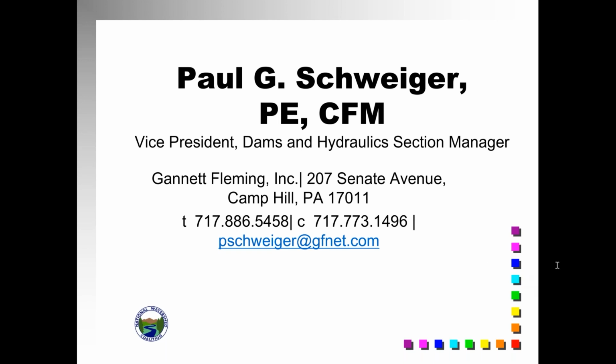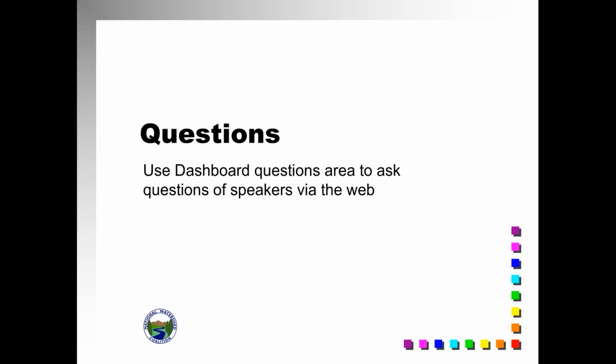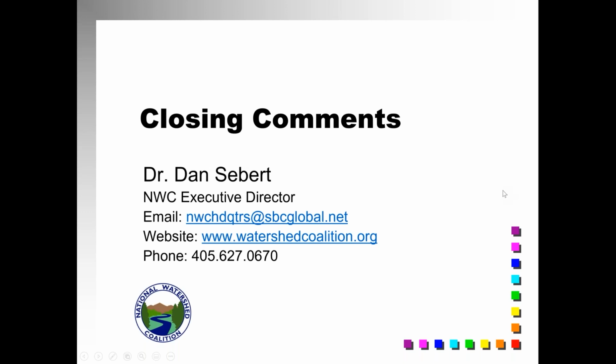A lot of modifications are often done with good intentions, but they have consequences that are not anticipated and can create a real problem. A good example was the farmer that built that ramp to get up over the dam and get to his fields, not realizing that he reduced the spillway capacity. There's an example in Hawaii at Kaloko Dam where the dam owner filled in the entire spillway, not realizing it was a spillway. They had a flood event, it overtopped the dam, and 8 people died as a result. So some of these modifications can have dire consequences.